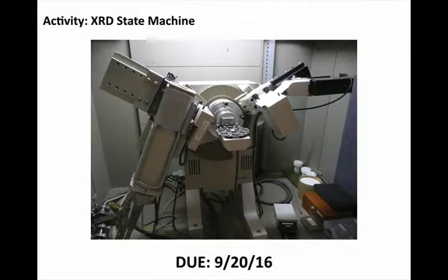They're going to go up, they're going to open a door, they're going to click a button, they're going to wait for something to happen, and you need to make sure, in this case, that it is safe. This is an X-ray machine. It could fundamentally hurt someone. So there would definitely need to be something like, if somebody opens the door and it's running, it goes to a shutdown state immediately.